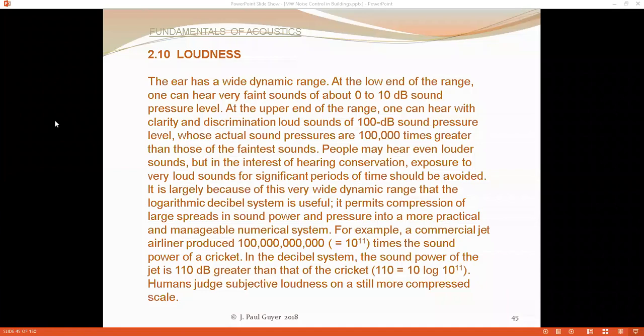And then the second knob that you've got on the sound level meter has two settings, fast and slow. And this sets the sampling rate for the meter. In other words, on the slow setting, the typical sound meter will sample or measure the sound being produced once each second.